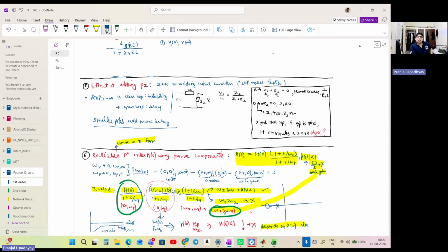This is something that we can extend to the idea of compensation also, where we know that by Miller compensation, what we typically do is, let us say that the poles were initially like this, right? So the first pole, this was the second pole. So in Miller compensation, what we do is that we split these poles apart, right? So this pole comes here, this pole comes here.